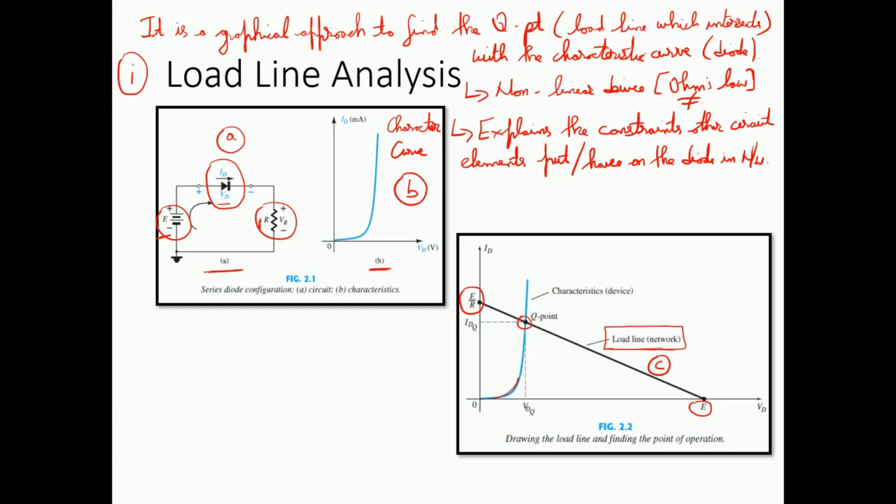We look at the circuit and we apply what is known as the KVL on this circuit. If you don't remember, I'll upload the lecture series on Kirchhoff's voltage and current law at the end of this lecture, and you can revisit those to refresh your memory. Kirchhoff's voltage law basically takes the algebraic sum of all the voltages in any network, and it should be equal to 0. So this is the mathematical expression of Kirchhoff's voltage law.